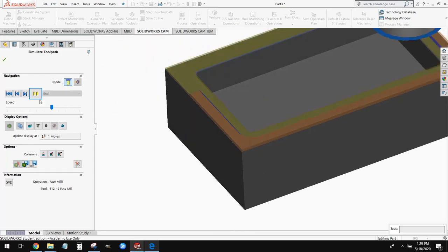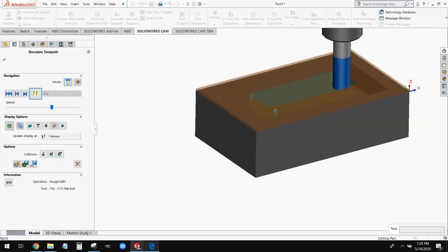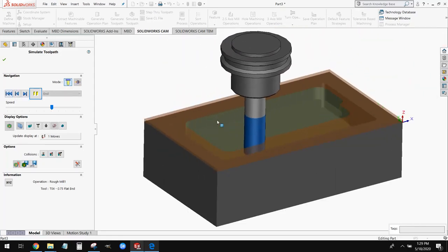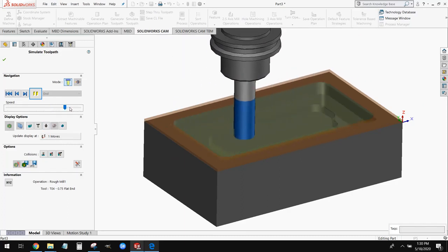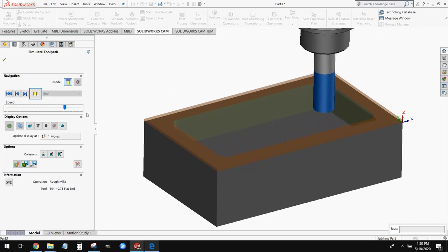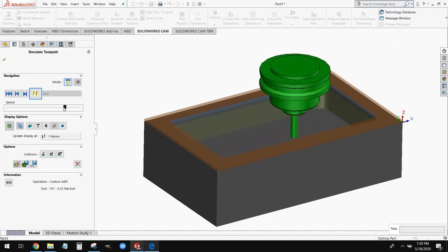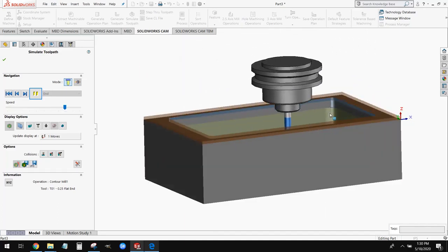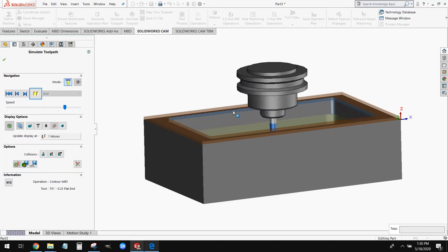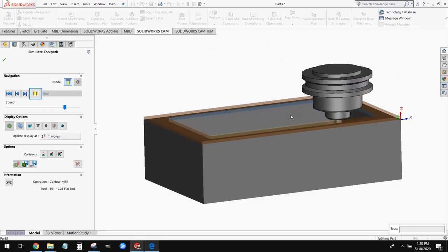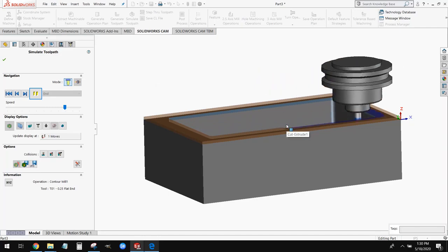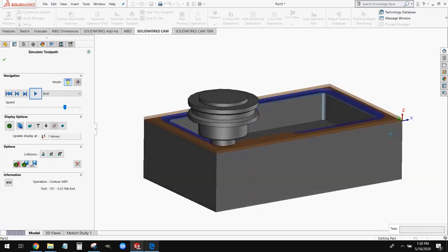from before. Now, you'll notice what it's doing is it's putting that face mill operation at the end. Now, we don't want this because from before, we still have that issue where that 1/4 inch end mill is crashing into our part. And like I said, it's going to damage our part, but it's also going to damage our tooling, and we don't want that. So what we're going to do, let's see right here, coming up in just a second. Yep, right here, right? It's still crashing